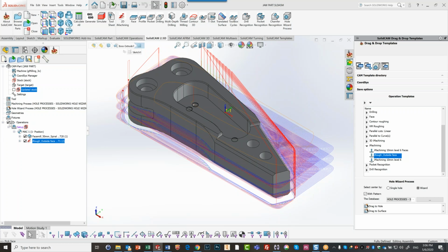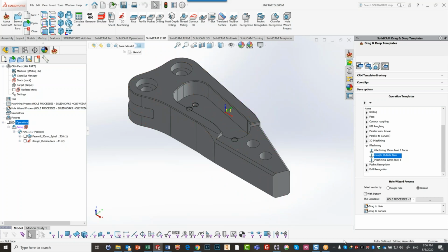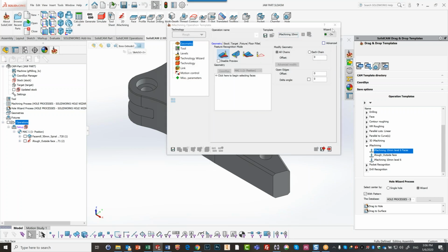Okay, let me get rid of the lines so we don't have to see them all the time. I'd like to now work on this pocket over here. So I'll do first a pocket operation with a 10 millimeter end mill with the eye machining over there. Drag it. Sorry, my mistake.